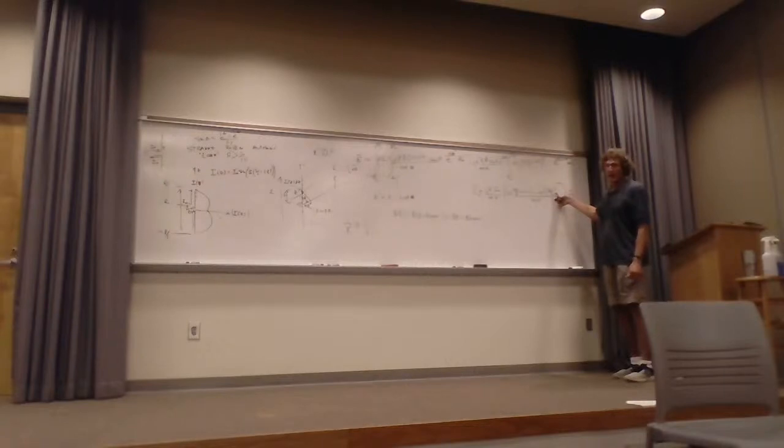And I'm going to tell you, this itself is the E field. To get the average power density, it would be 1/2 magnitude of the E field squared over eta, right? You all know what I'm talking about. Then we could go ahead and integrate the power density over the whole thing, get the power radiated, we could find the radiation resistance, and we can get the directivity.